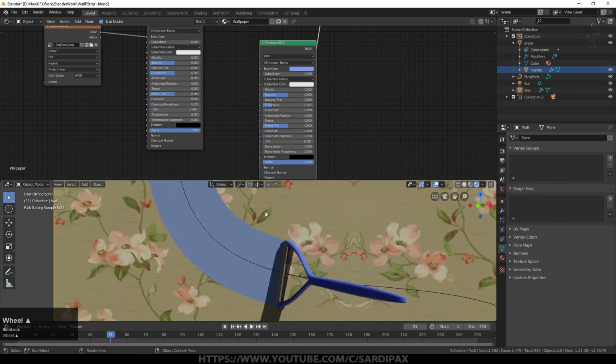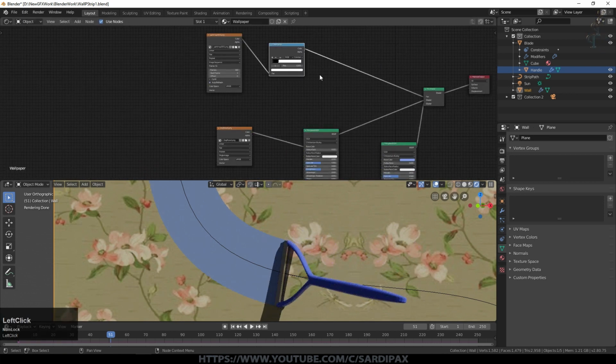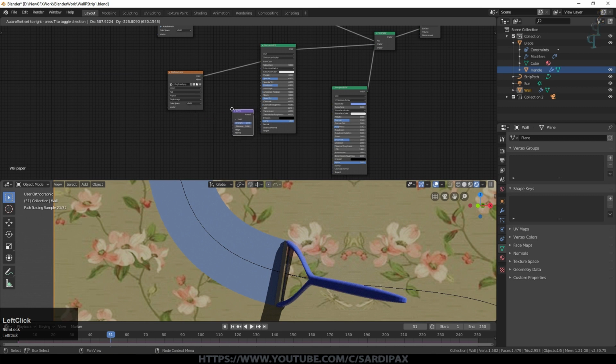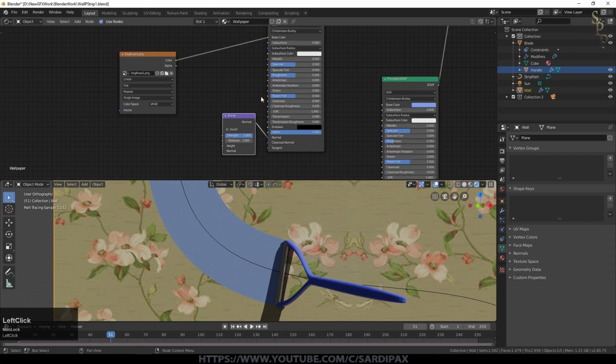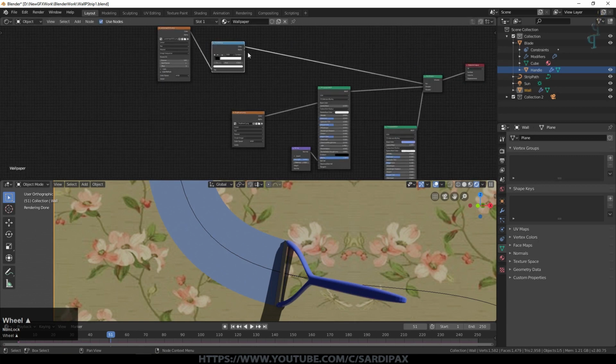So we obviously want the wallpaper to have a certain thickness to it. So what I need to do is use this material here, this dynamic paint map, to create a bump. So I'm going to add a vector node, which is a bump node, and drop that in there, input it into the normal. I'm then going to take another of the outputs from, I know this is quite small at the moment, my color ramp output, into the height there.